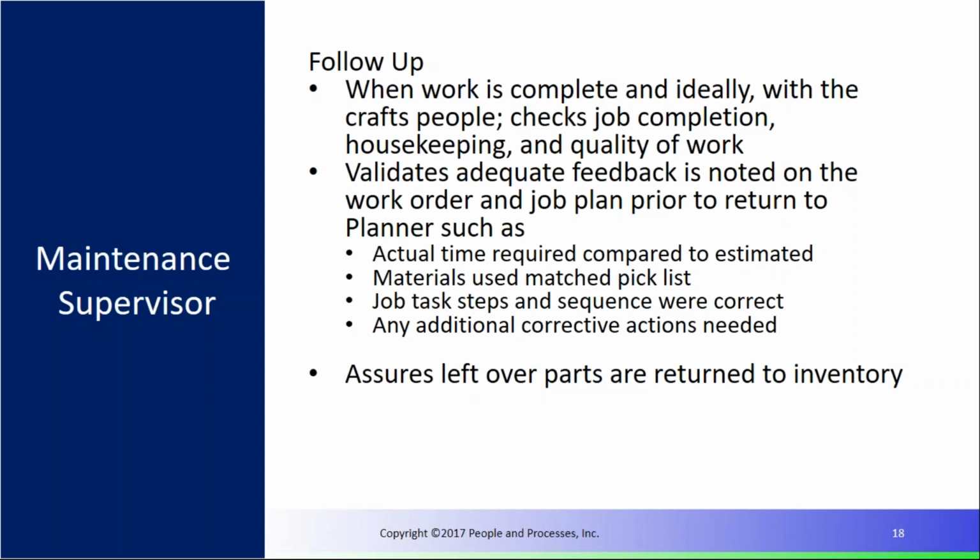We're looking for things like precision maintenance steps: gaps, fits, torques, clearances, belt tension, and any other items. Hey, you forgot about this gasket that we needed, or this seal, or whatever the case may be. So we want to update the job plan as part of that. That's the role of the planner, but you have to give them the information to make that happen. And then we want to make sure that any excess parts, we return back to the stockroom.